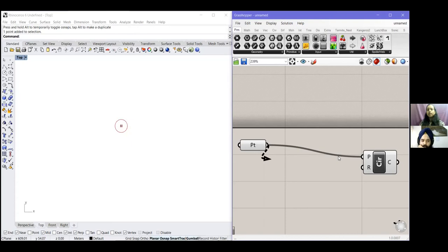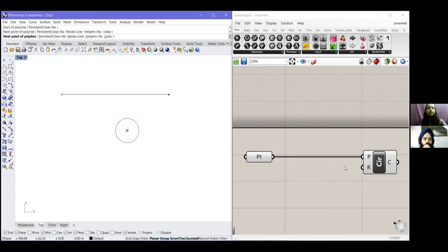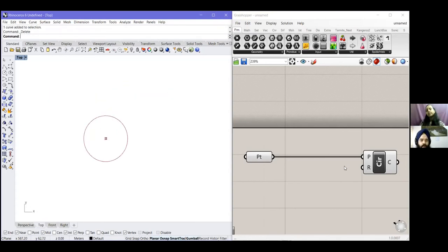The point that we had on Rhino, right? So if I just make a line here for a reference, and I move this circle closer to the line, sorry, the point closer to the line, the circle itself moves. So if I move this point here, the circle moves there. I made that line to just show you the reference, and I'll just delete that. And now we have the circle. Now this is one circle, and it was easy to make on Rhino also.